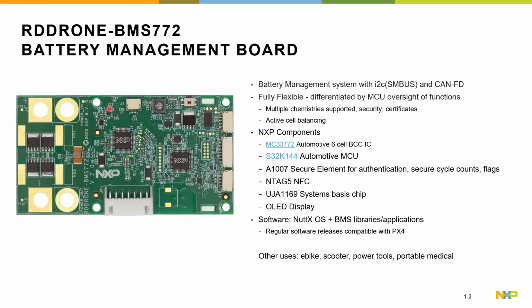I wanted to also point out that these battery cell controllers are designed for automotive use, and they are designed to cascade up to larger cell count. So here we only have 6 cells, and it's built for a traditional LiPo battery type of configuration. But there are pins that allow you to daisy chain these up to very high voltages.